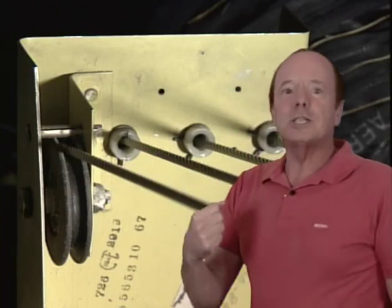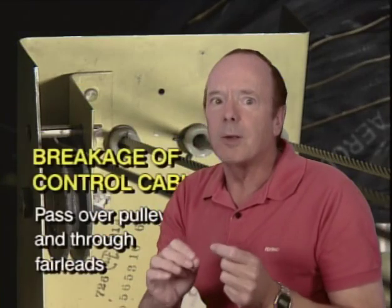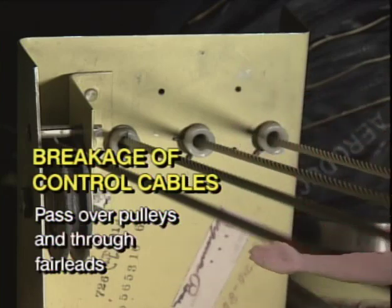Now, is it possible control cables could have broken wires where they're swaged to terminal hardware, such as turnbuckles and ball terminals? And the answer is yes, it's possible. They could have wires break at those points, but on a properly rigged cable, you're much more likely to find broken wires at points where the cable changes direction and makes contact with other parts, where it passes through pulleys and through fair leads.